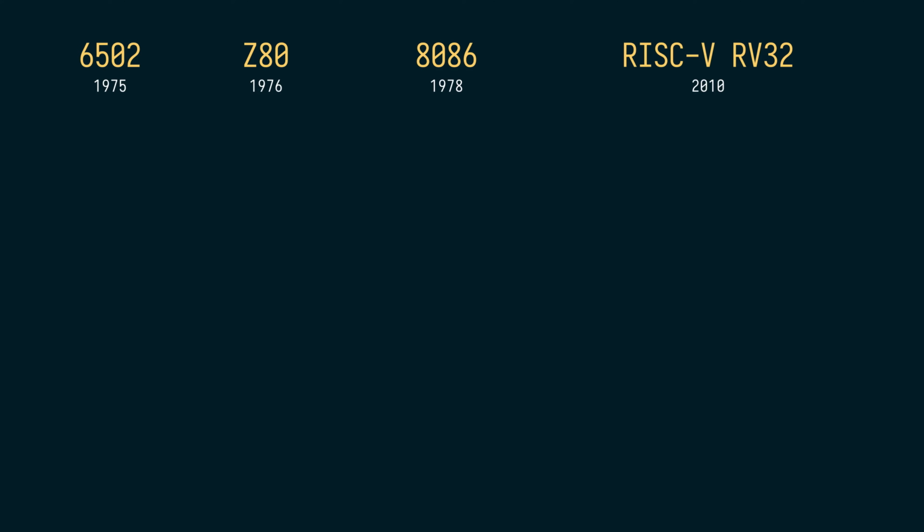In the early days, the 6502 processor, which among other things drove the very popular Apple II computer, had only 4 8-bit registers, and of those, only the A register was really used in computation. It provided one of the operands for the arithmetic instructions, while the second operand was loaded directly from memory. X and Y were indexing registers that could be used to modify the memory addresses accessed by load and store instructions, and SP was used as a stack pointer, which tracks the location of intermediate results kept in memory.